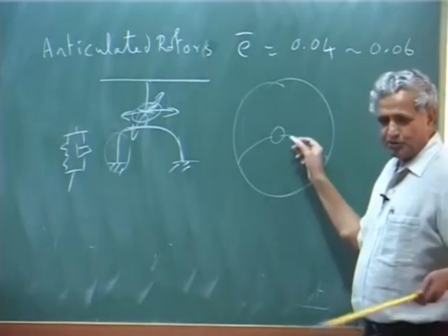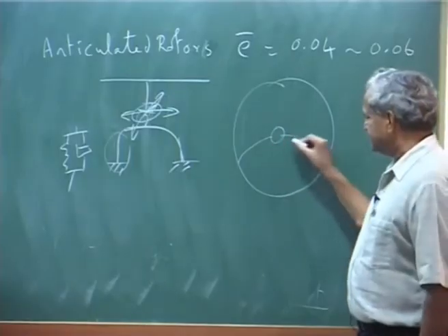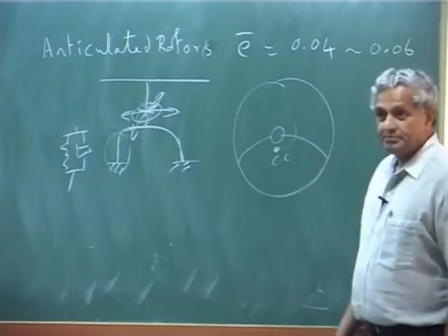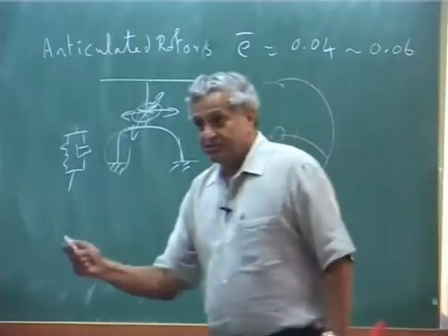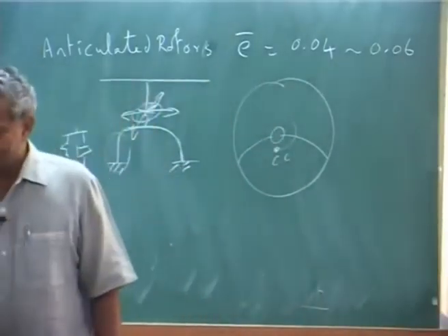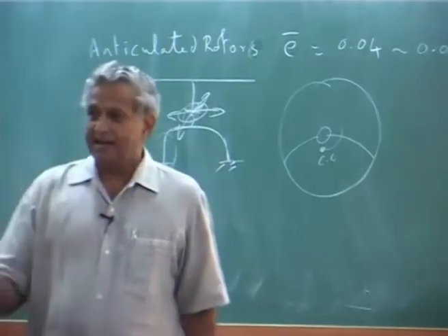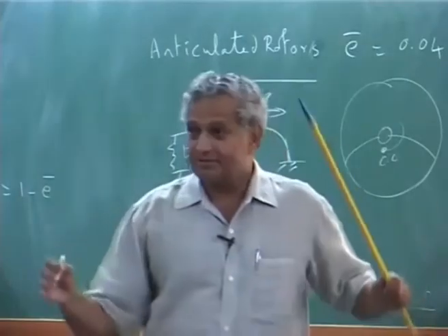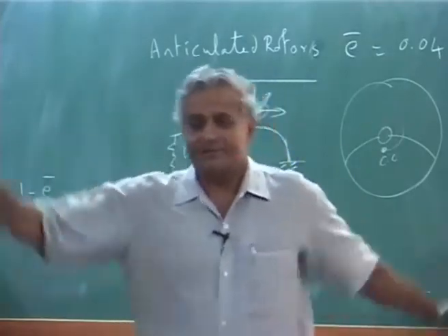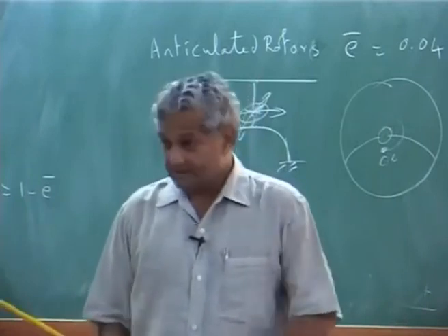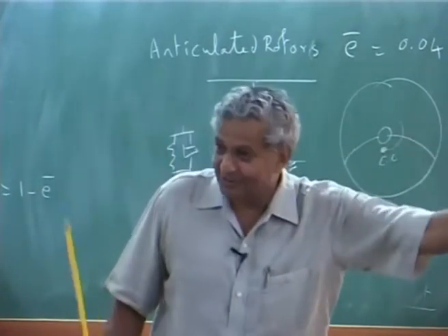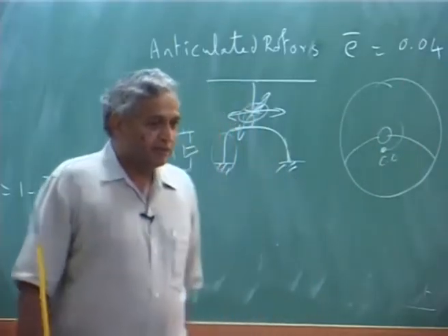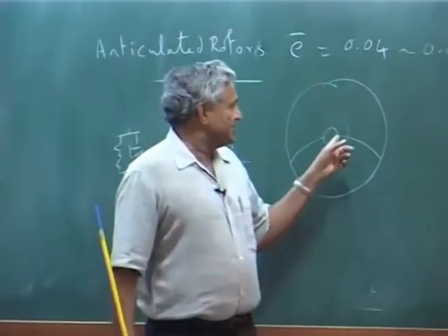When it bends, I am just drawing for two bladed. The CG of the system is here, and when it rotates it churns. That means that is giving an imbalance or unbalanced mass which is going around, and that combines with the fuselage motion and it will start heavily oscillating, and it is very catastrophic, because the moment the blade touches the ground, the blade is gone. It's a teetering, what they do is they make it stiff in plane.